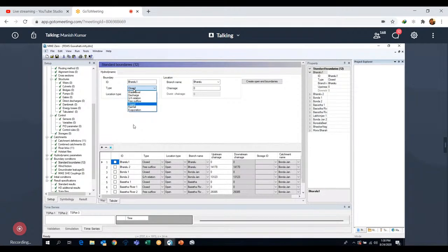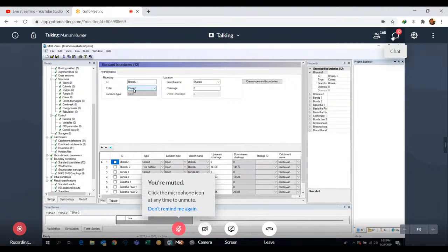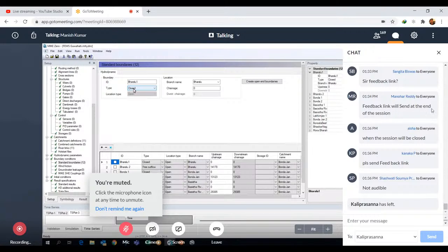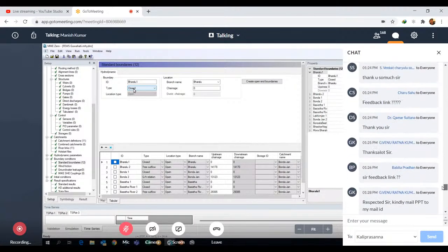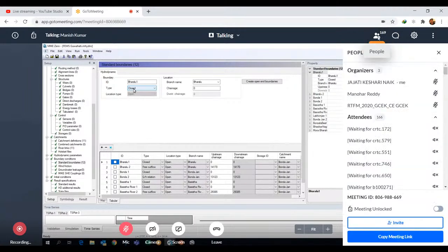So these are the options. Normally we provide water level or discharge at the starting point. Similarly, your model is not ending at Varanasi. So how will the water leave after your model boundary ends? We need information afterward. There you can give various information.